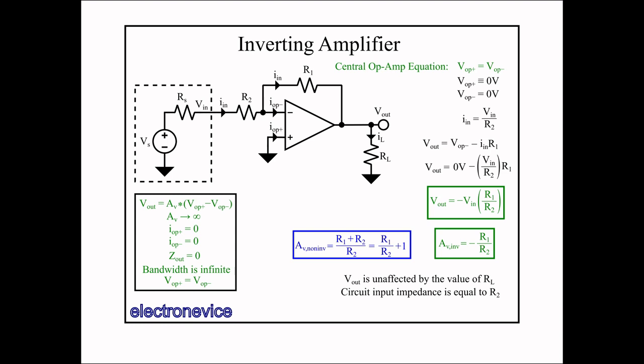One might not consider this to be a very good selling point, as a gain magnitude of less than 1 is not actually an amplifier and can be easily done with a resistive divider. But it becomes far more important if one is attempting to apply gain to some frequencies, but not others, as in a filter. For example, if you put a capacitor in parallel with R1, it would amplify low frequencies but attenuate high frequencies. Such a circuit is called an integrator and will be discussed in future videos.